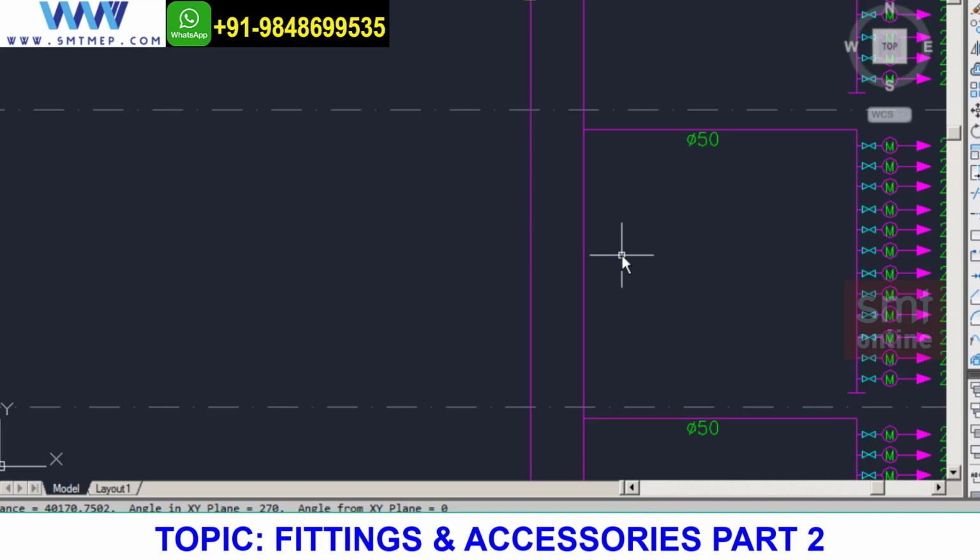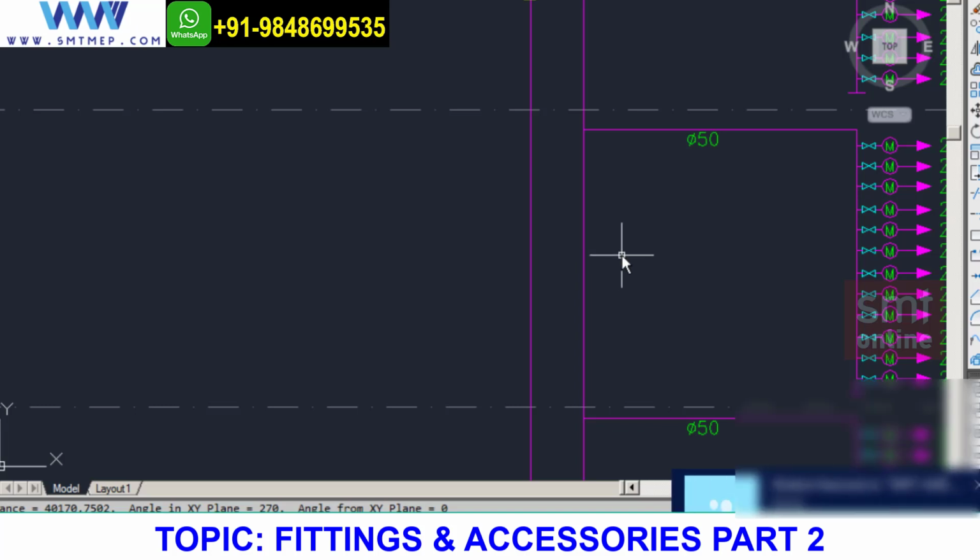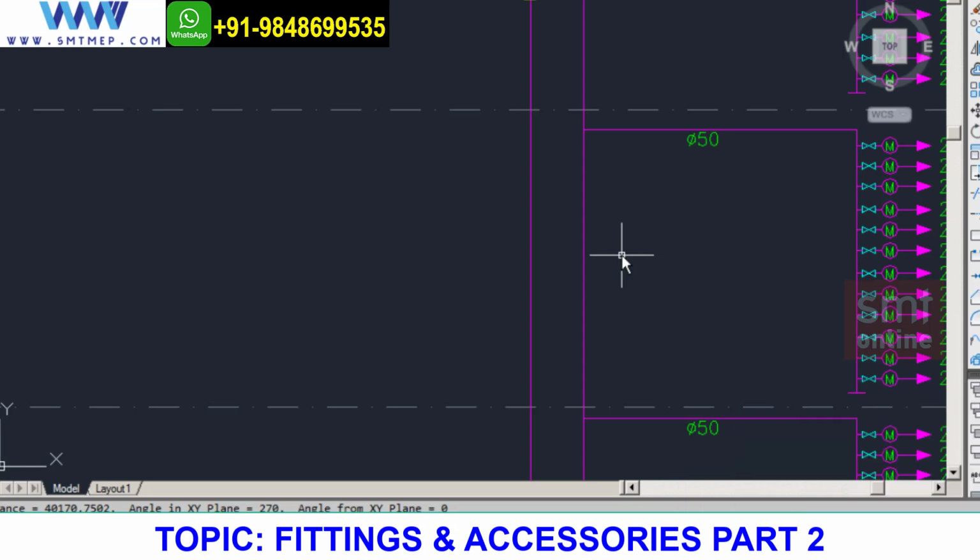So I do have a formula to calculate this, that is P equals H times 0.433 psi, where P is the pressure I need to find out, that is nothing but the pressure exerted at the bottom. Okay. And H is what? The height. H is height, and it should be in terms of feet. Write down that H should be in terms of feet units. And 0.433 is a constant.